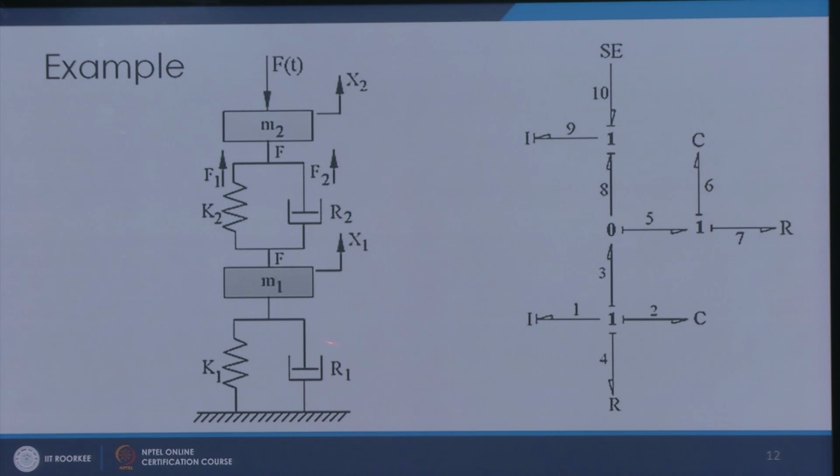Now, the difference is that here instead of Vt, the velocity is now decided by this mass. Okay. So, this system will be subjected to the difference of velocities. Okay. So, to draw the bond graph model, it is very simple. Here we create a 1 junction corresponding to this velocity port of M1, and I attach an I and C and R corresponding to this. So, I have I, C and R. So, this way this completes this portion, and here I have this M2.